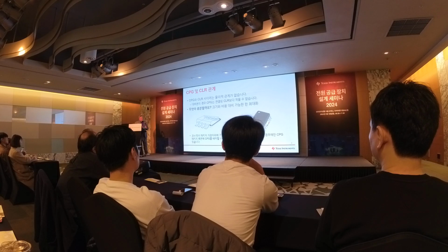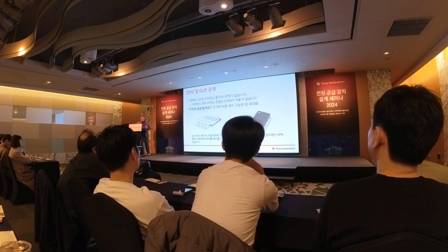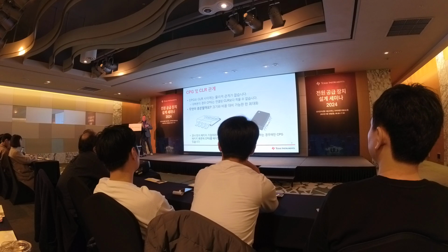It could be around the outside of the package as well. In general, there is no case in which the creepage can be less than the clearance. And you'll always want to try to maximize both whenever possible. It's a trade-off between the size and the cost.